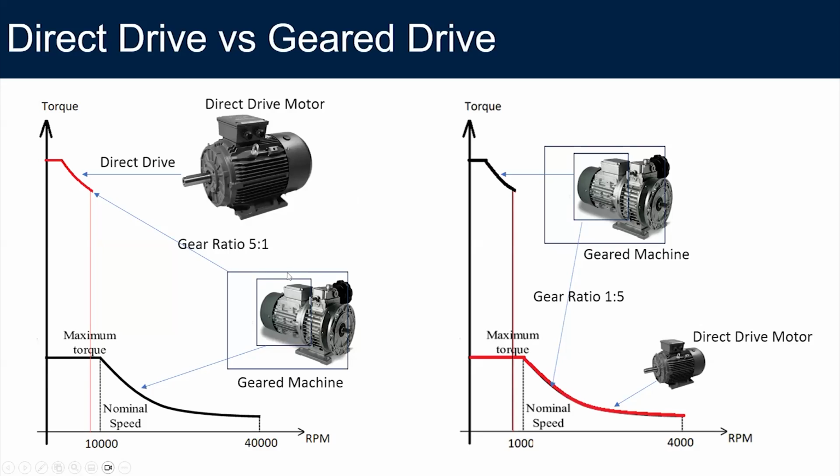However, we see that if you compare the weight of the direct drive option to the right side and the gear drive option to the left side as well, the weight difference is not that much in certain applications, but then in very specific applications, we find that the gear drive motor or the gear drive generator has certain benefits in terms of packaging. So I'll go through a couple of examples that we encountered during our projects here in Melbourne.